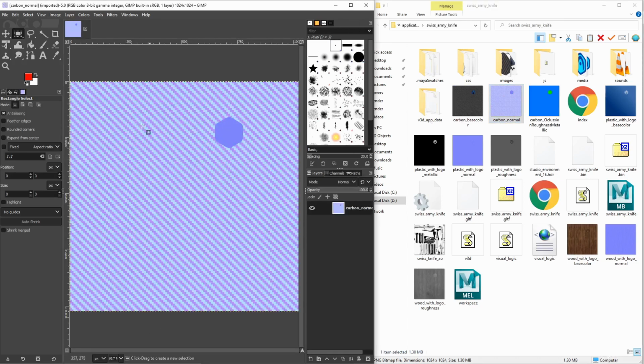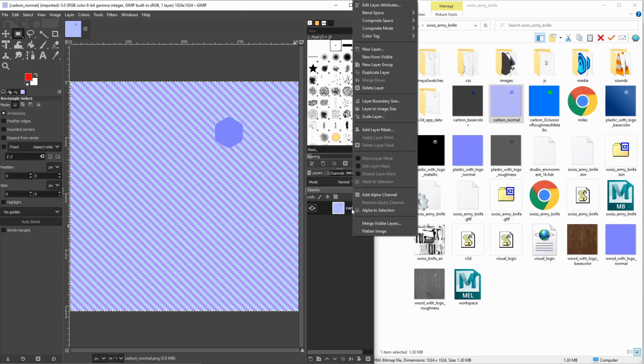Let's also check the normal map. Although we are not going to convert it to JPG, it is important to ensure that there is no unused alpha channel in it, since it adds up to file size. In our case, there is no alpha channel, but if your image has it, you should definitely remove it from an image to make it smaller.